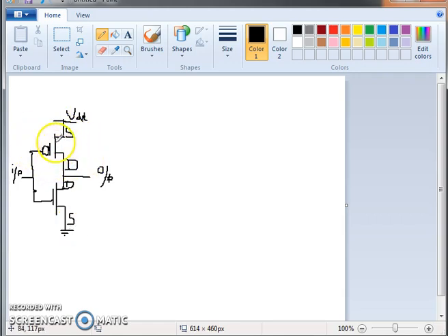The diffusion of PMOS should be shown yellow in color. This is the NMOS transistor. Diffusion of NMOS should be shown green in color. Formation of a transistor is poly crossing diffusion. It forms a transistor. Polysilicon, which is a gate, is red in color.